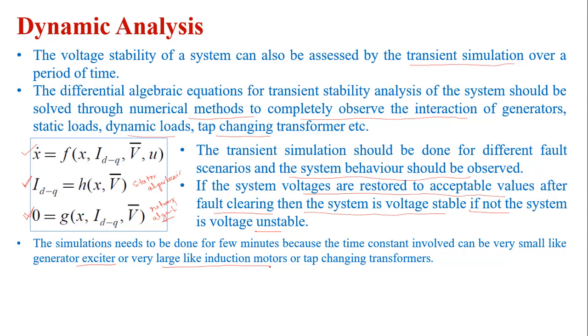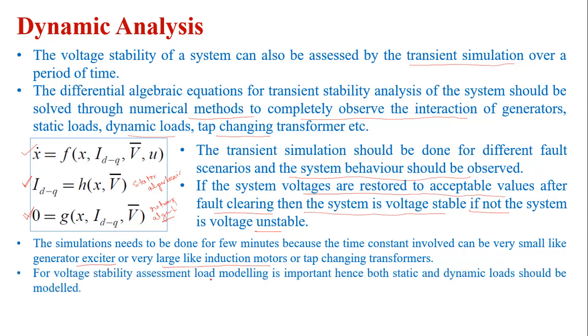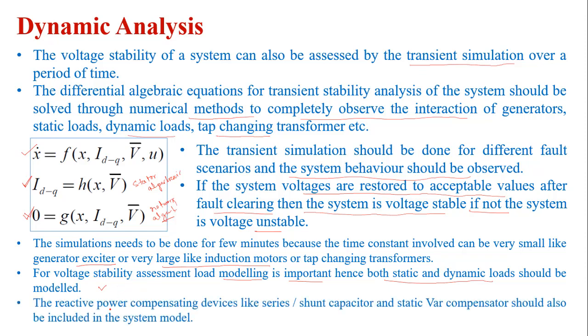So therefore the time period should be taken appropriately. For voltage stability assessment, the load modeling is important, hence both static and dynamic loads should be modeled appropriately. The reactive power compensating devices like the series or shunt capacitor and static power compensator should be included in the system model. So let us now consider the small disturbance analysis.